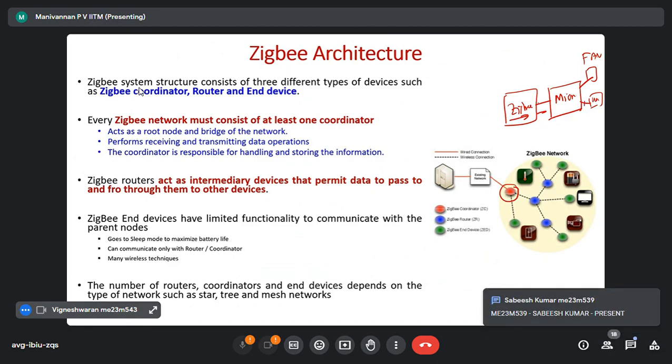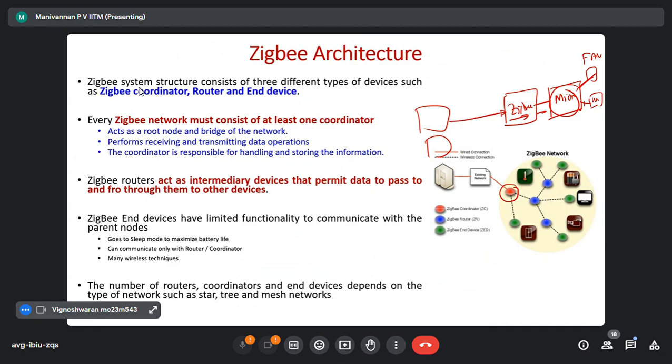So here you have to write the program which will control. You transmit data from your wireless device to the Zigbee device, it receives, and whatever data comes here, goes to the microcontroller. The microcontroller decides based on the command it is receiving. You have to program this microcontroller. Understood now, sir. Okay, thank you.